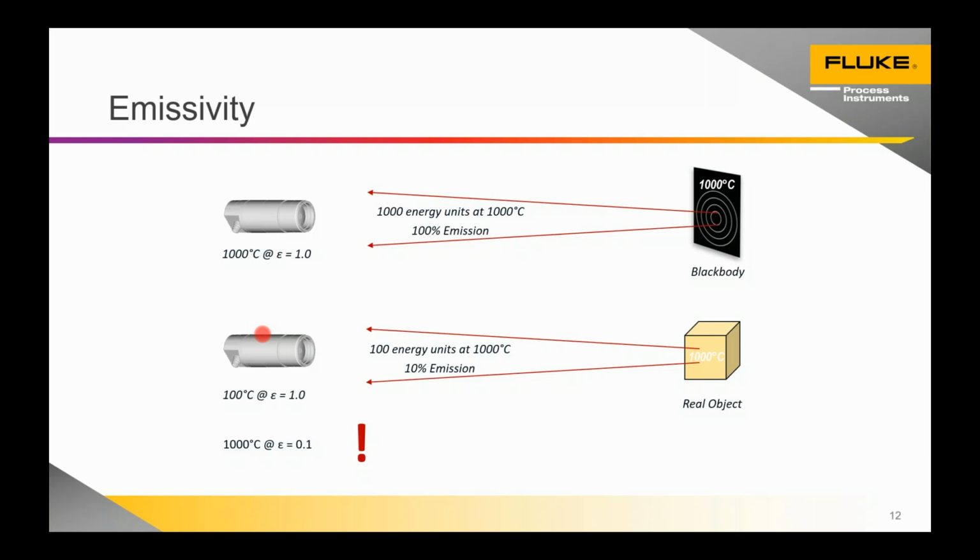It's often advised, if you've got applications that are fairly rugged, that it's possible we receive a sensor with a dirty lens. We always give before and after values, so we report on as found, make a correction, and send it back. Sometimes calibration is as much a maintenance, but purely as a device in terms of its own drift in ideal situations, you don't need to calibrate them. They don't drift and have to be offset and gain adjusted every year. They're very stable in that sense.